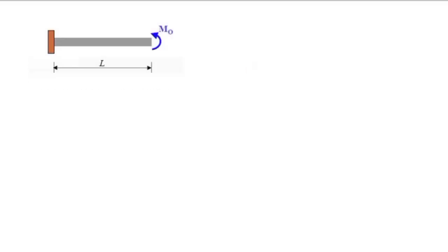Ayan. So we have here the second figure. As you can see in the second figure, so first, ang gagawin natin is establish ano yung mga reactions natin. Since this is a cantilever beam pa rin, we have 3 reactions to the support since this is fixed. So kung ito ay point A, we have here AY, we have here AX, and we have here the moment at A. So if we are going to summate forces vertical equal to 0, taking the upper direction as positive, then we could say that